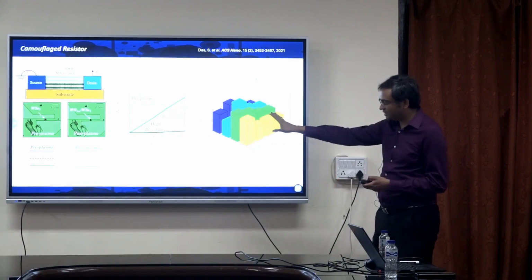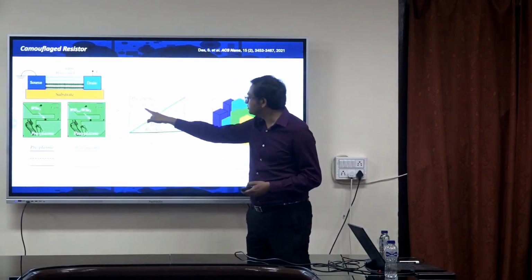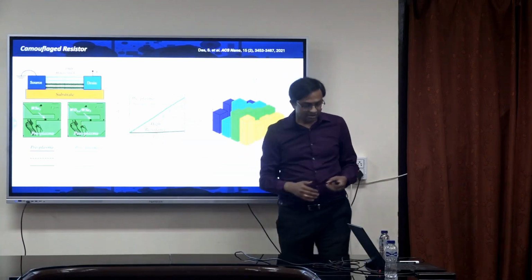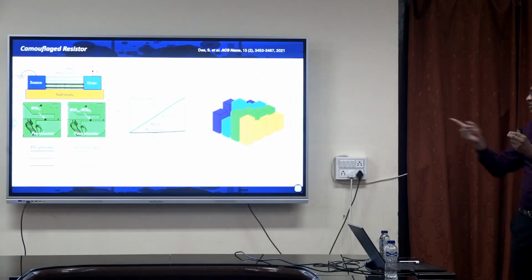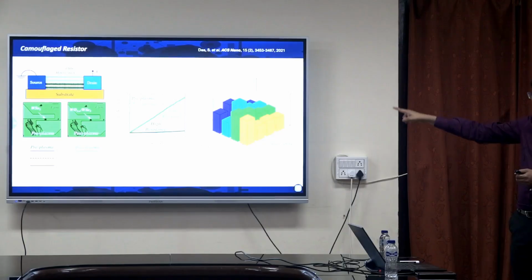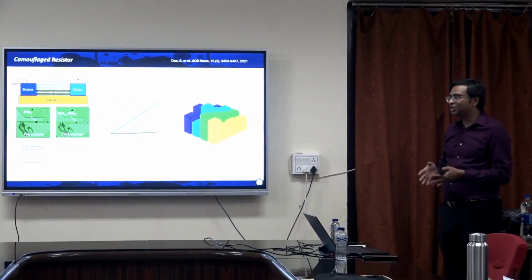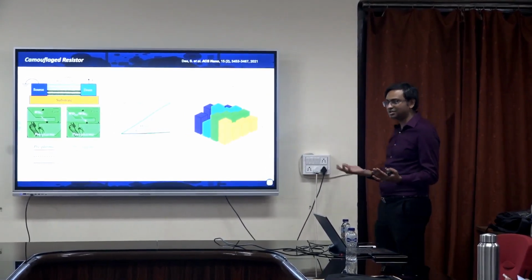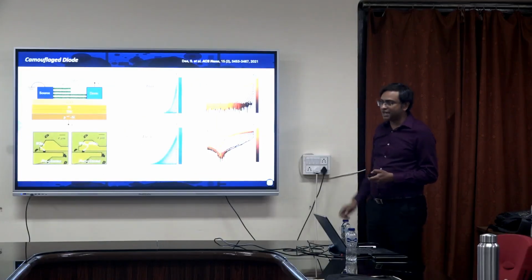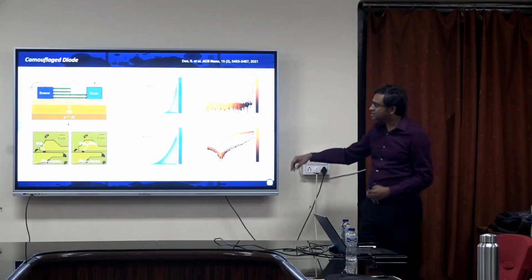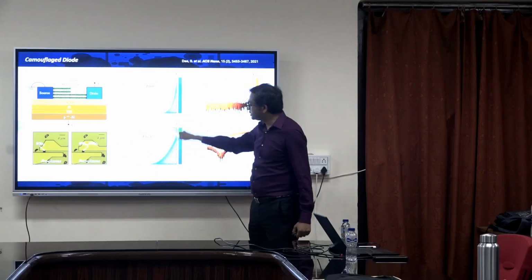These are some more data, just showing what happens. You see pre-plasma, post-plasma. I can use it as a resistor, because generally you cannot change the resistance value of a resistor, right? But now through oxygen plasma, I can get two resistance values without changing its appearance. So your adversary will not know whether it's a high value resistor or a low value resistor, correct? That's one. I could do it for a diode, depending upon how much I dope this side versus the other. You can see the two diode characteristics are different.